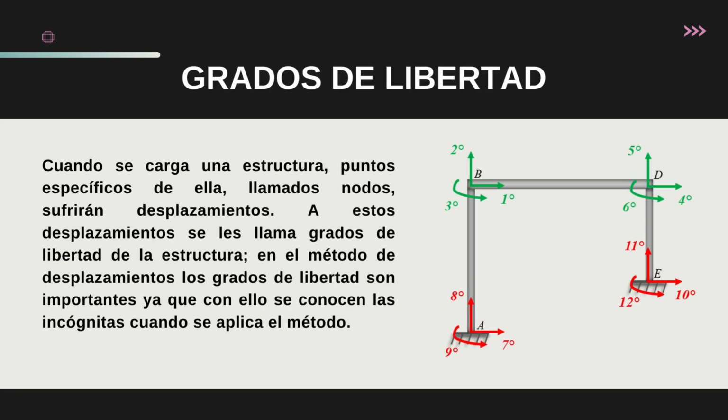Degrees of freedom. When a structure is loaded, specific points of the structure, called nodes, will undergo displacements. These displacements are called degrees of freedom of the structure. In the displacement method, the degrees of freedom are important since they are the unknowns when the method is applied.